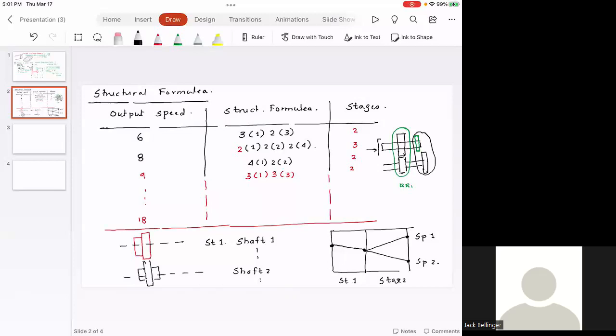So you will have a clutch here, and then you have a shifter assembly. What this would do is you will disengage, you will have a shifter that will push the gear shaft towards right, and then the second stage or the second reduction ratio, which is RR2, will get engaged. So you can achieve multiple reduction ratios using the configuration that I have shown here.